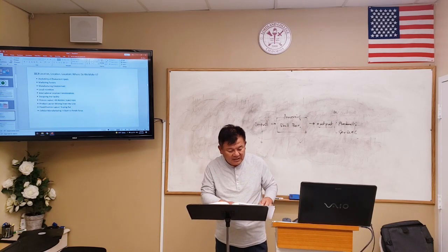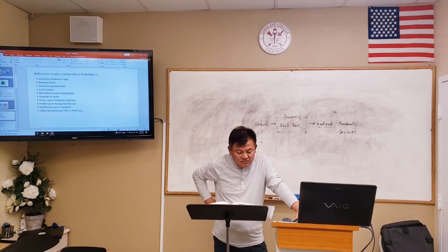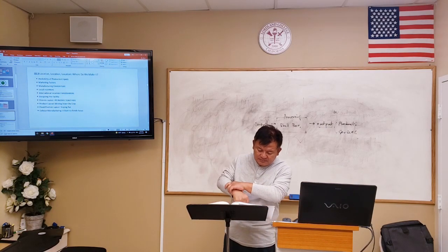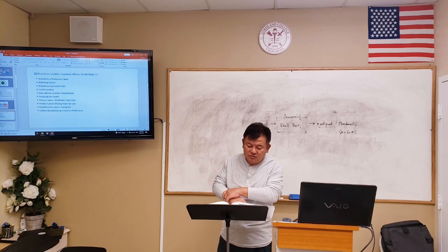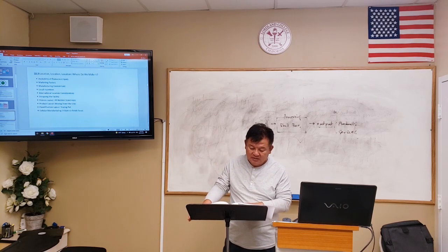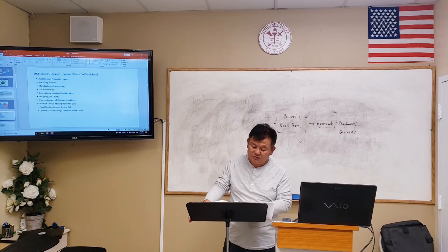Okay, and also process layout. Process layout arranges workflow around the production processing. All workers performing similar tasks are grouped together, and products are passed from one workstation to another. It's moved on, but not necessarily to every workstation. So process layout is also a very key factor for deciding location.